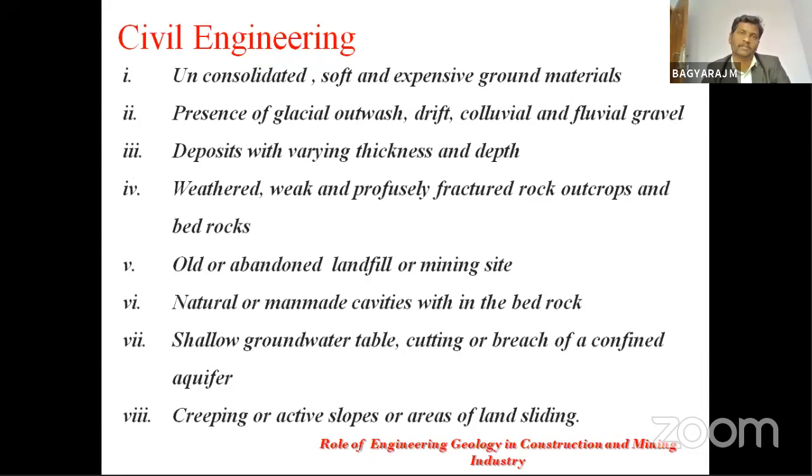We may be able to find unconsolidated, soft and expansive ground materials. We may come across glacial outwash, colluvial and fluvial deposits with various thickness and depth. We may come across weathered, weak and pervasively fractured rocks, outcrops and bedrocks.